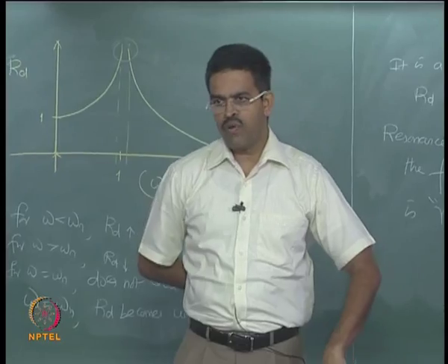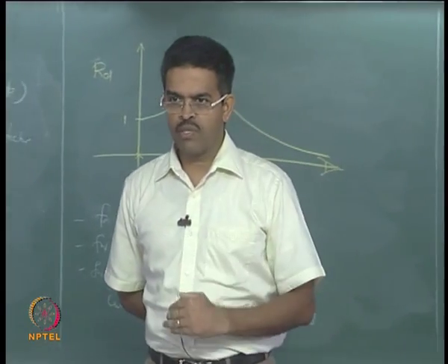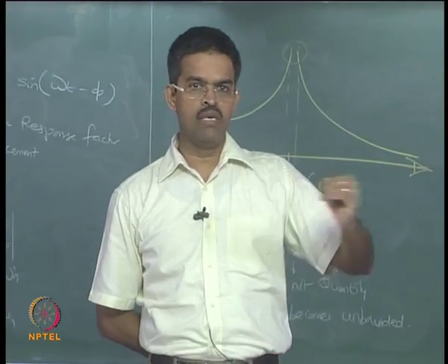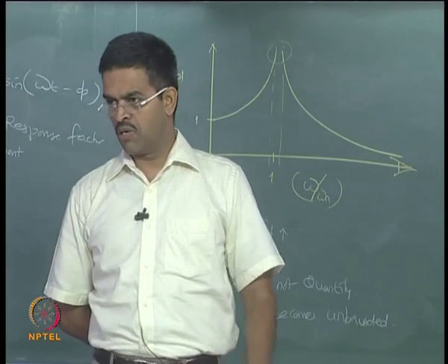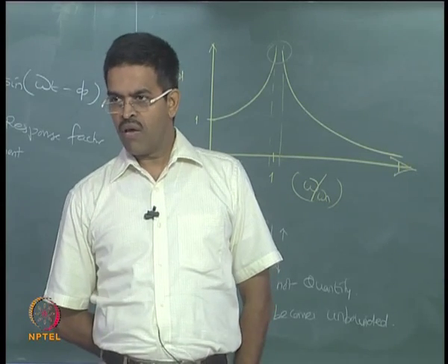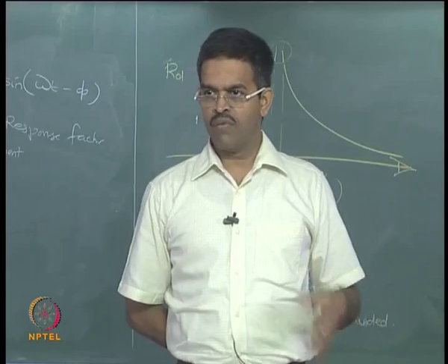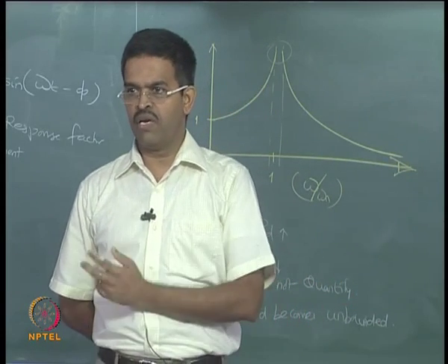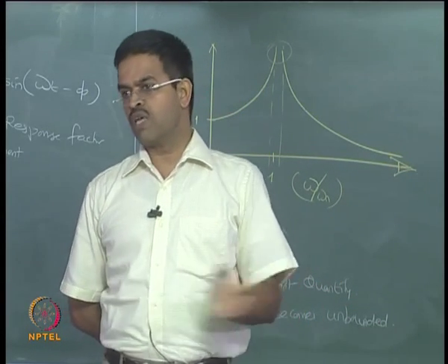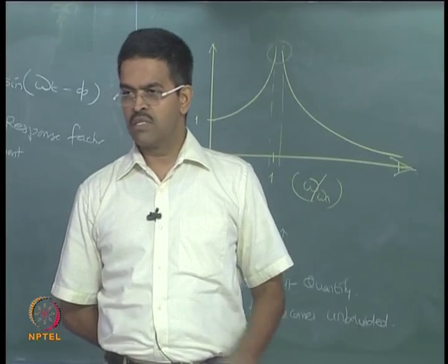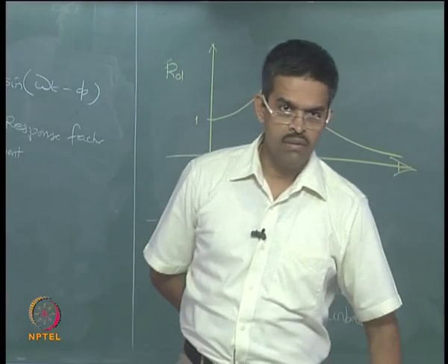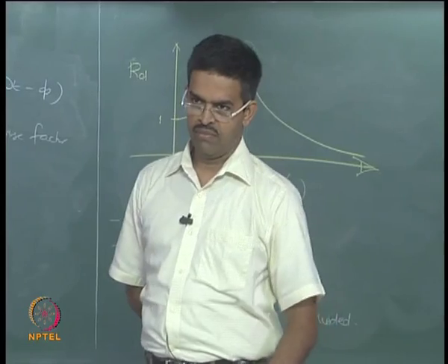M has a component from variable submergence, because the platform is not completely in water, not completely in air, it is partially immersed in water, and the wave surface is not still water, it is not horizontal, it has elevations which are sinusoidally defined. At any given instant of time there is a possibility that the submerged volume can alter, therefore M will alter.